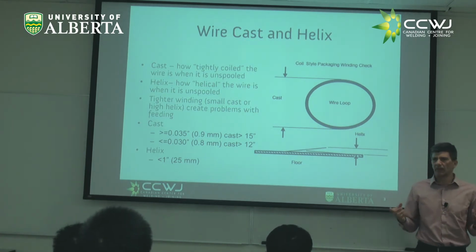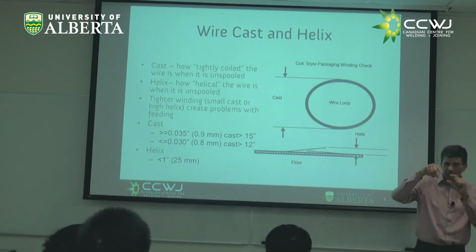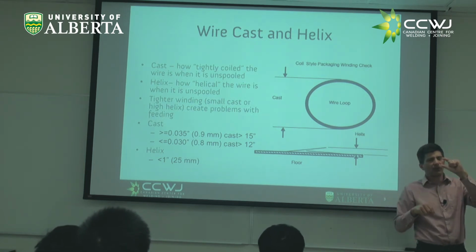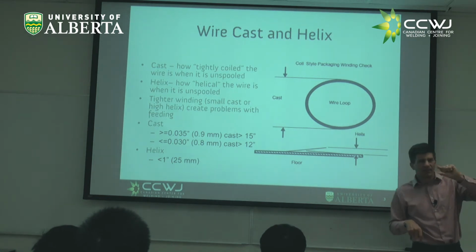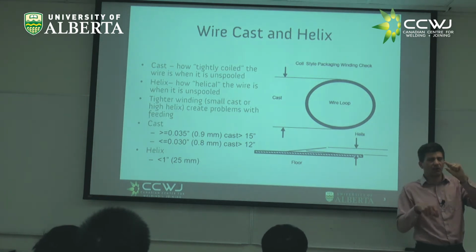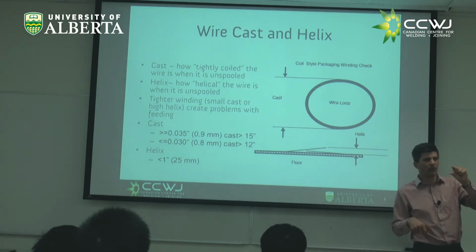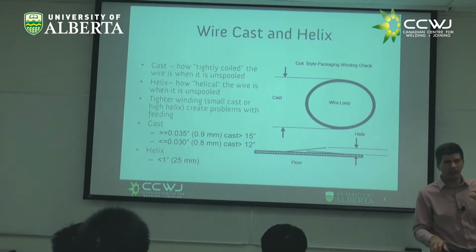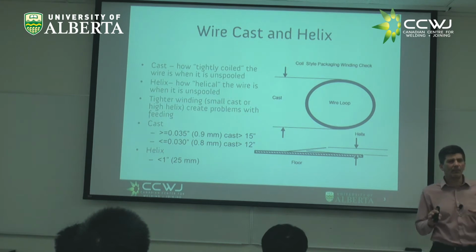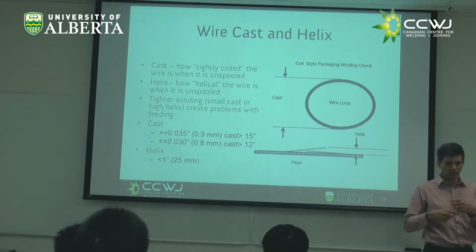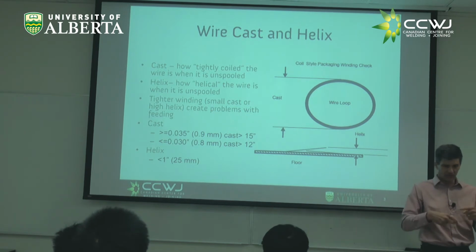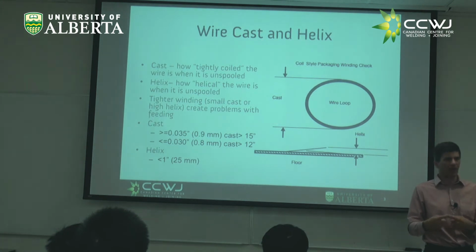When you see the welding machines, you're going to see that the wire has some amount of free wire extension that is called the electrode extension. If the wire is crooked, you're going to have a wandering arc because the tip of the wire is moving all over the place. If it is straight, it's better, right? Welding companies, the suppliers, go to great lengths to give you a wire that, when you unspool it, goes straight. Actually, they twist it as they spool it such that it would be counterbalanced.